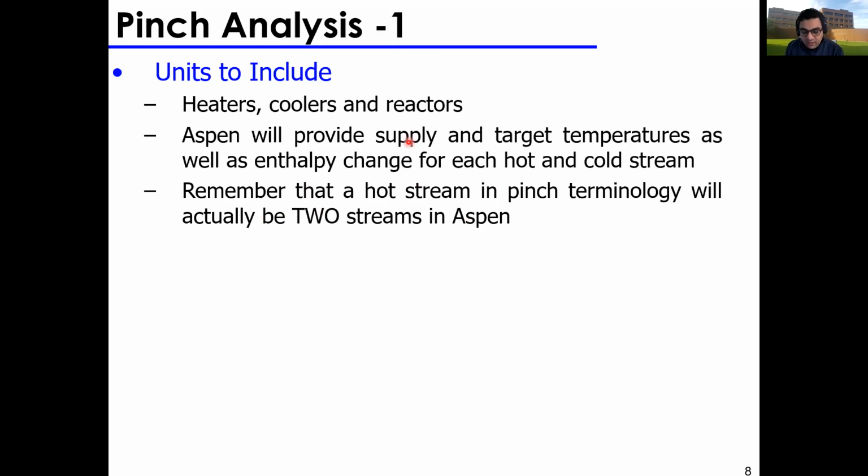And these can result in significant savings in your plant, and it's actually very important to consider these types of optimization activities when designing a process. At the very first stage, at the initial stage, once you have your base case and you're starting to size all this stuff, you need to do your basic pinch analysis to get a good idea of your process thermodynamics. Because once you know where your pinch point is, you can understand at what streams can I cool and at what streams can I heat without violating thermodynamics.